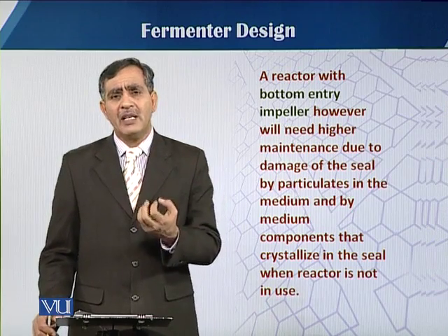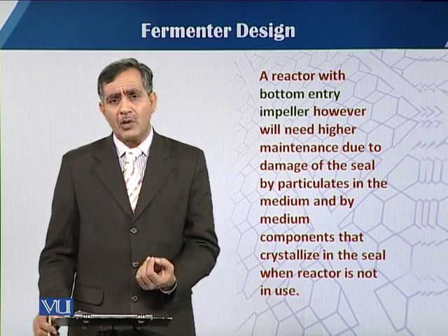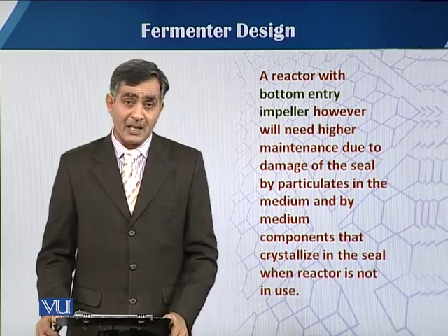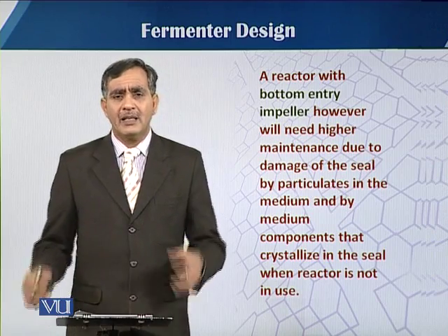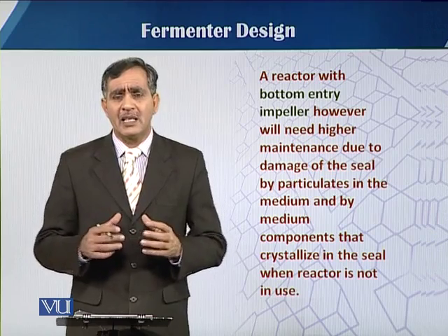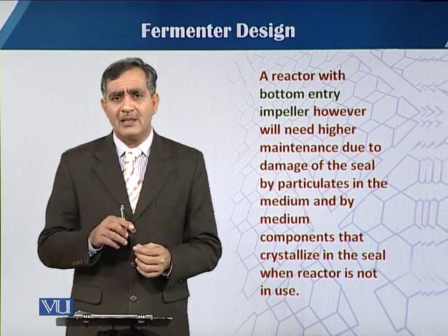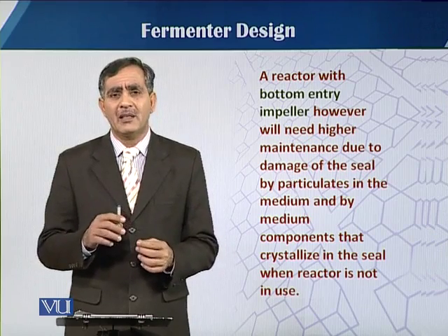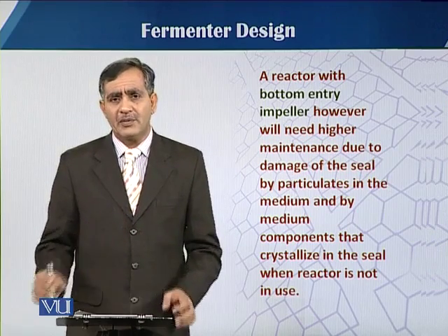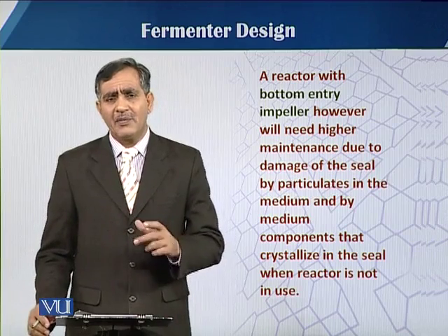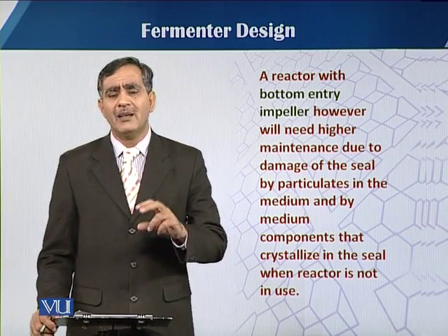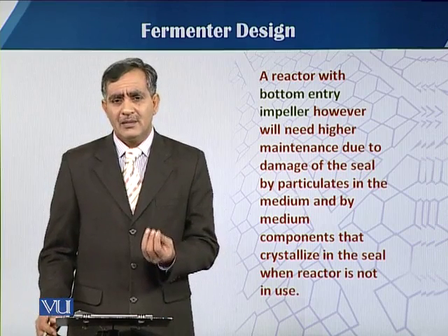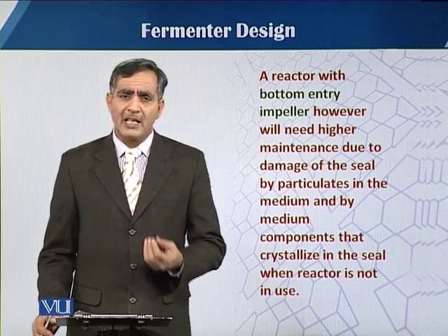But when we fix the motor on the bottom and the shaft enters from the bottom, there is also a limitation, because in the medium there is precipitation of crystals, and those crystals cause some mechanical disturbance with the shaft and the seal, and then the life of the seal is very short. So there is a limitation when the motor is attached to the bottom.